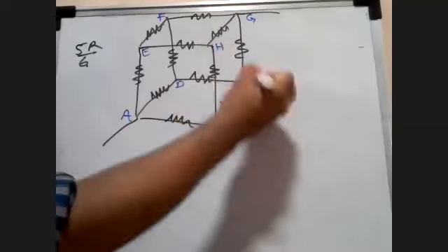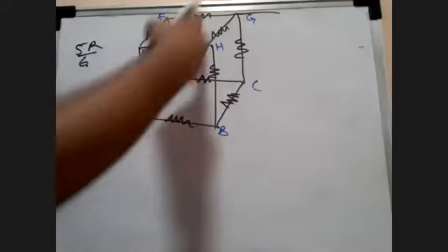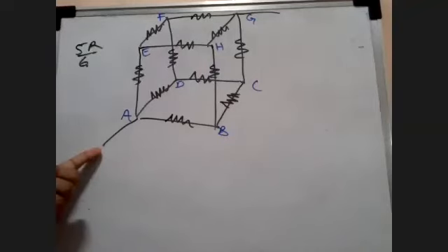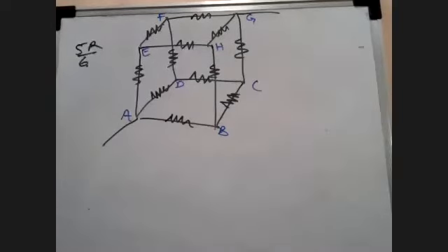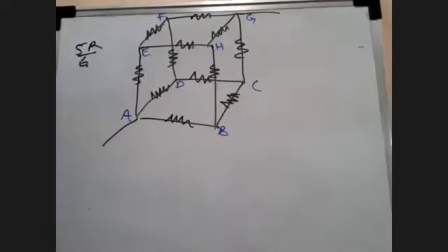This letter be H. Okay, have I named all? Yeah. So if I am able to do this, what we should be able to find out is if I have to find out this equivalent resistance between A and G, most simple thing is just take a highlighter for now and just see what all paths can you use from A to G.